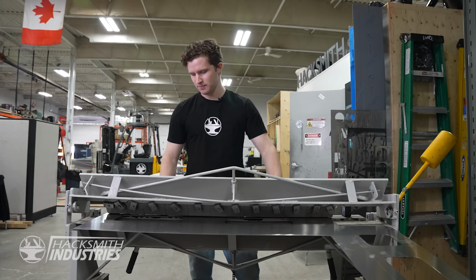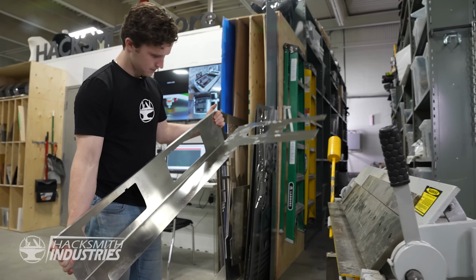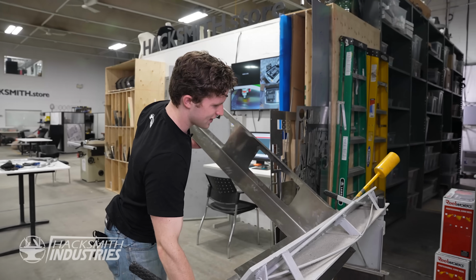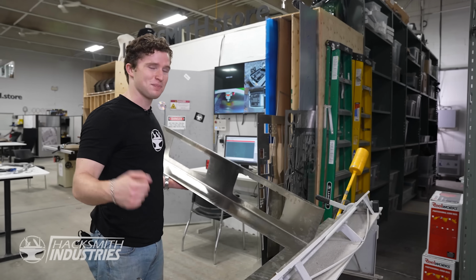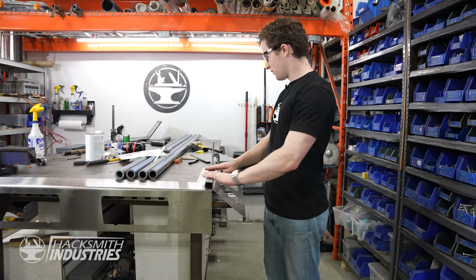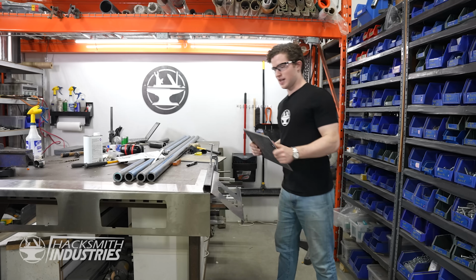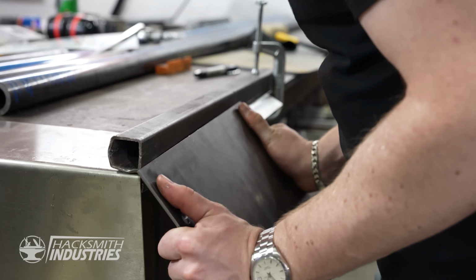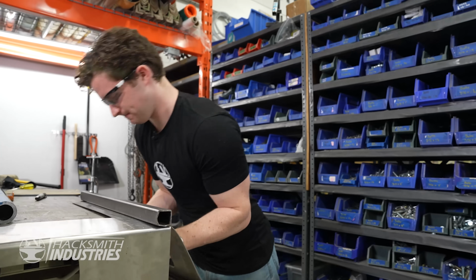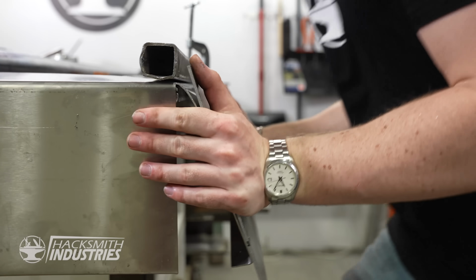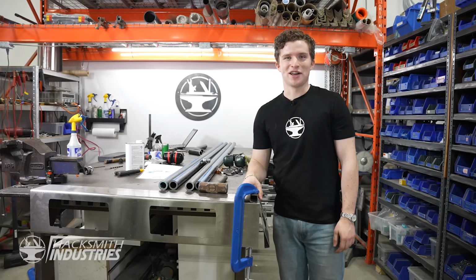Okay, we're gonna use this box brake to bend our sheet metal. So the problem with these edge bends, when you start bending, it runs up against the other side of the frame. So what we need to do is take this out of the brake, go to a table, and just bang it the old-fashioned way with a hammer. So what I've done is I've attached a little bar stock up top, attached to this thick metal table, and I'm gonna use this thick mild steel, just basically as a plate to push it down and get that 90-degree bend. It's pretty MacGyvered, but that's what we do here. It looks pretty good. We gotta do that 4 more times.